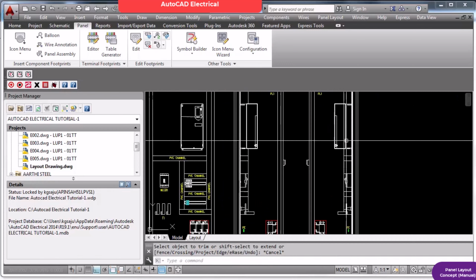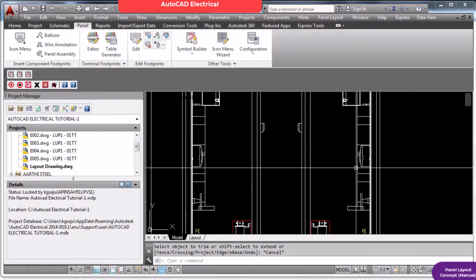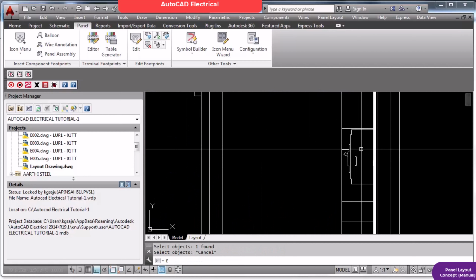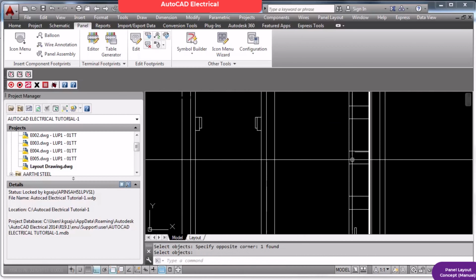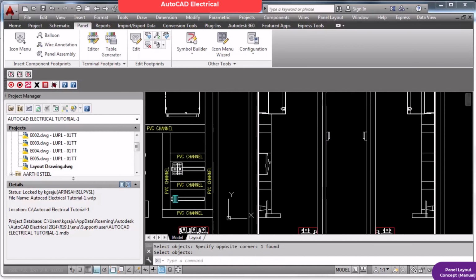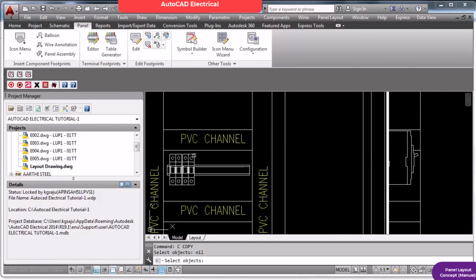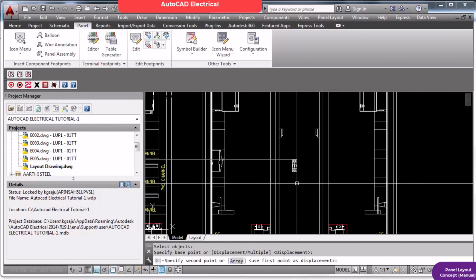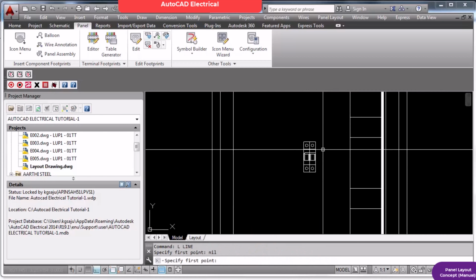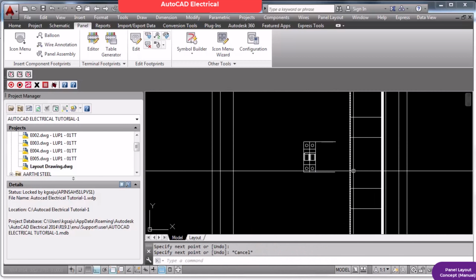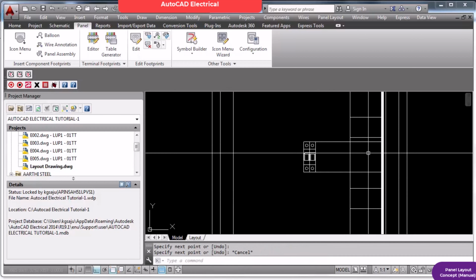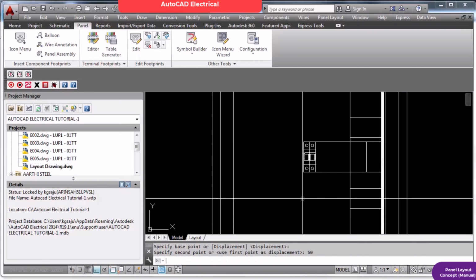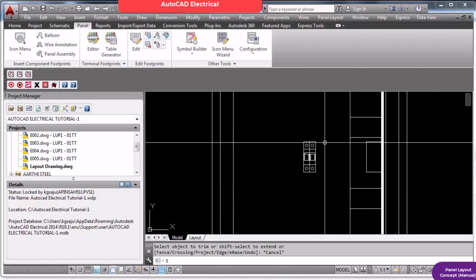When you view from the right, when you view from the left, this PVC duct, you can't see this duct also because the drive comes first. When you see from here, it looks like this. Then this MCCB won't come here, instead the PVC duct. So better you delete this MCCB, and here's a MCB. So make a side view of this MCCB too.